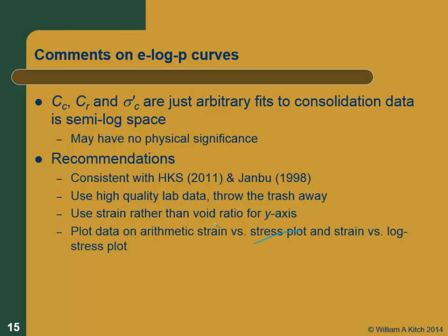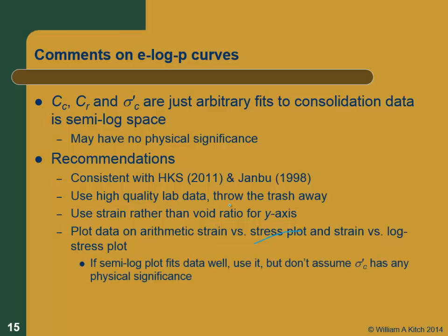And do check. We've said this repeatedly now. Do look at the plots both in arithmetic space and semi-log space, and then make a conscious decision about which one's the appropriate one for you to use for your problem. If the semi-log space works, use it. But just don't assume that the sigma prime C has any physical significance. And if you want to use the secant modulus method, that's great. Go right ahead. Whichever one's the most appropriate.